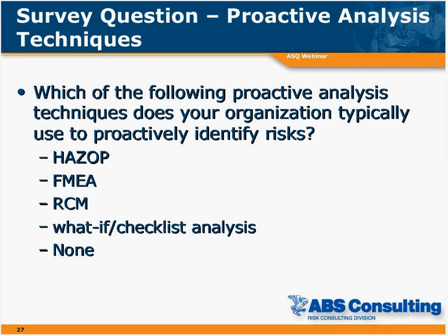In many of these, they're using various techniques, but if checklists are used improperly on complex systems that really require one of the techniques, such as FMEA or fault tree analysis, that's a problem. So it's a good idea to go back and see what proactive analysis techniques have been used at your facility.